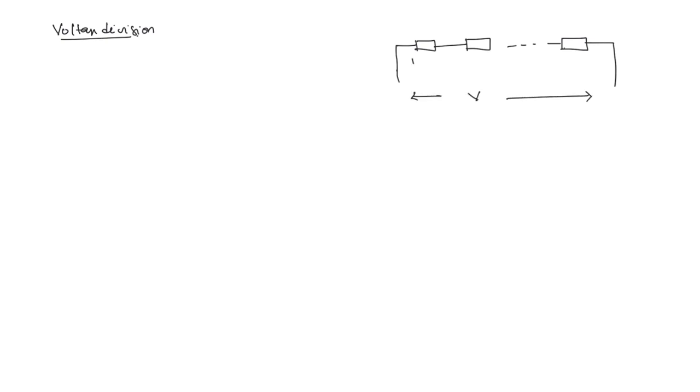Next we will discuss voltage division. So here also it is just like in the case of resistances, just that in place of resistors there are going to be impedances. Okay. So voltage division will come into the picture when there are a number of circuit elements in series. And if the total voltage across the combination is given as V, then what will be the voltage across each of the elements? That is what voltage division will give, right? So these are all phasors. So don't forget to keep the bar.